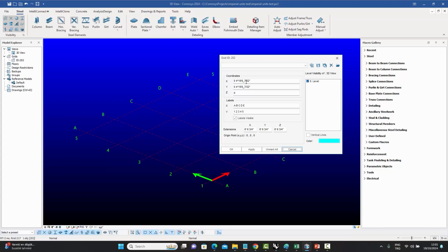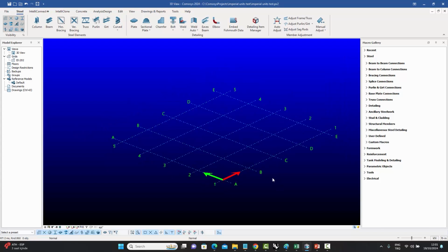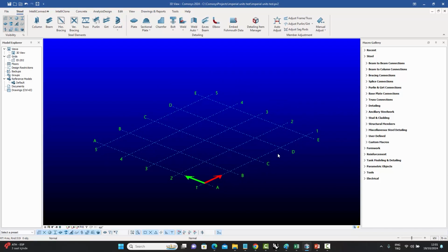Now we have the underscore over here. Normally you won't be required to do this, but this is only required in places where you can have multiple inputs separated by spaces. So in those cases, you have to fill the space with an underscore. For example, if I were to say 4 into 22 feet, now in the x direction, I've got 22 feet going like that.